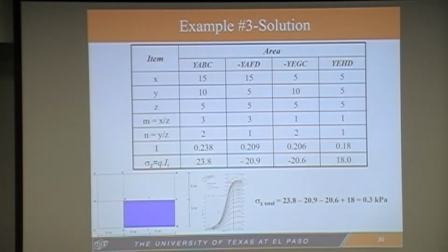That makes sense, right? Where do you think would be the highest magnitude of the stress? Dead center of the load. Center of the load is correct, and right beneath, right? So right at the contact. So that would be the maximum stresses. If you do the calculations, in fact, you will see that that is going to be roughly 1/4 of the contact pressure. So I'll leave that up to you, so take a look at that.